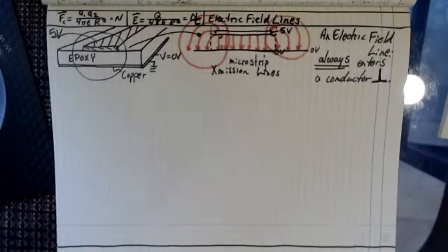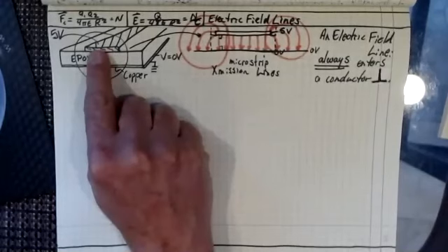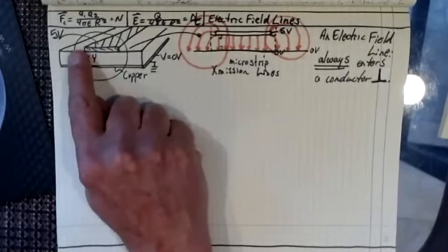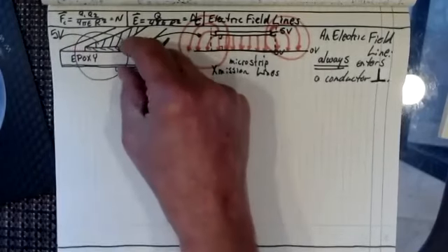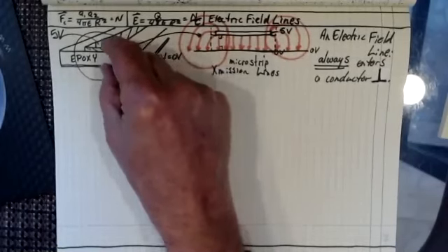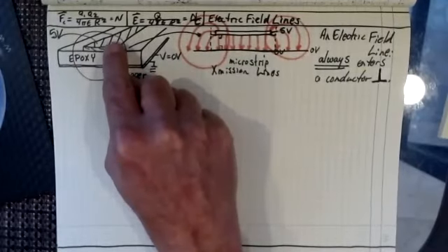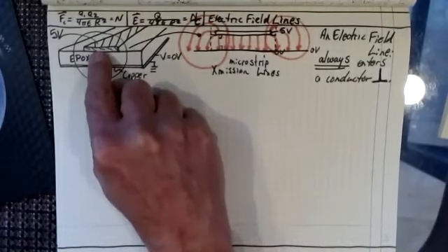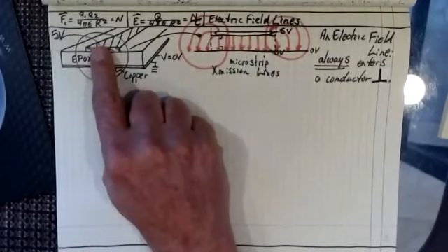Those high frequency trace lines have to be designed so that the width of the trace and the thickness of the printed circuit board all fall within the design, so that you match the characteristic impedance at high frequency, radio frequency.